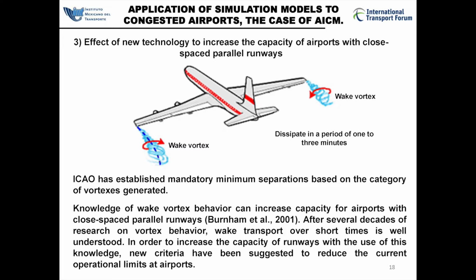Knowledge of wake vortex behavior can increase capacity for airports with closed space parallel runways separated by less than 2,050 feet. After several decades of research on vortex behavior, wake transport over short times is well understood. In order to increase the capacity of runways with the use of this knowledge, new criteria have been suggested to reduce the current operational limits at airports.